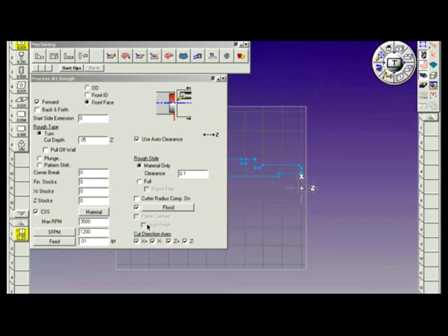If you have a need for a can cycle, simply turn off auto clearance, make sure your clearance values will clear the part, and then go to full, and you can use the preferred canned and the auto finish. In this case, we'll stick with auto clearance and material only. The cut direction axis will come into play shortly, and I'll explain what those do in the subsequent operation.